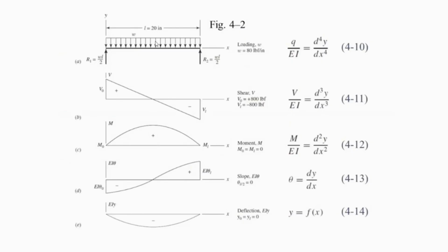So you can proceed here by starting from the load intensity function. By integrating these expressions, we can find the deflection function, and here we see the graphical representation for each of these corresponding functions.